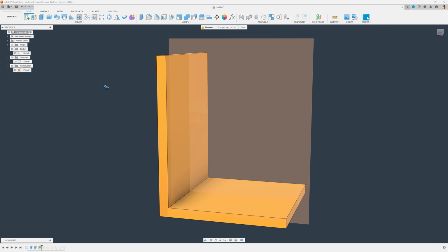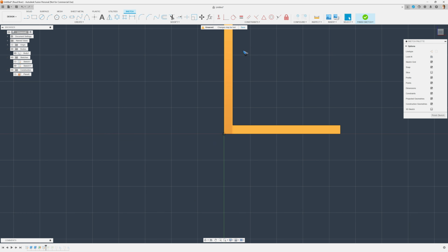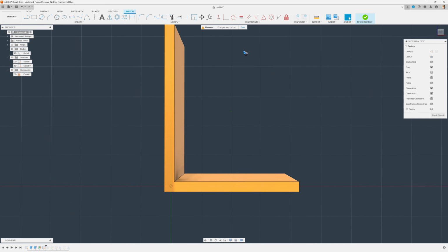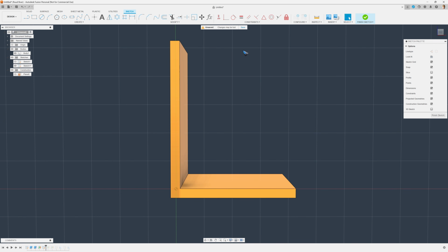We're now going to make a sketch on that new surface. Create sketch, click the surface, and then it's always a surprise where Fusion places your stuff. Let's zoom in a little. Let me hit the line command, L for line. The cursor has changed. What I want is to draw a line between these two surfaces. But as we can see, it doesn't snap anywhere. We have to do something first. Let me exit the line command with escape.